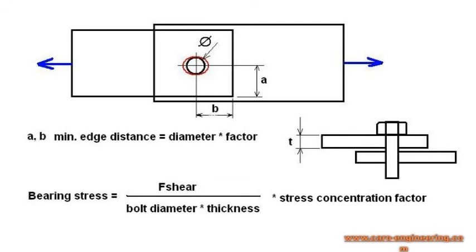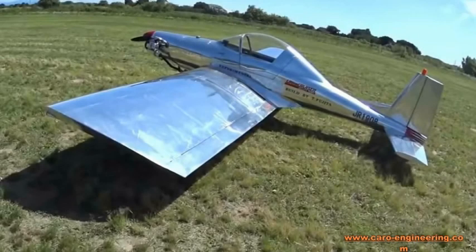The bearing stress allowables depend on the material of the sheet and are valid only for a certain minimum edge distance of the hole. If the load is too high, the hole will become elongated and the material will eventually tear out. After the structural analysis for the airplane is completed and the airplane was built, the results need to be checked by test. It is not possible to account for all the factors and combinations of loads on the structure, including fabrication tolerances and other errors.